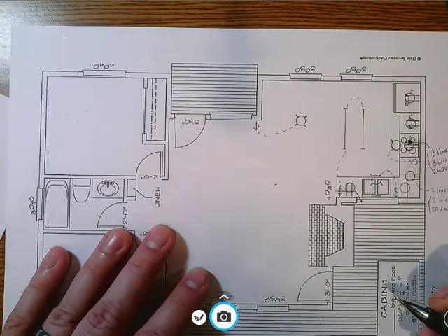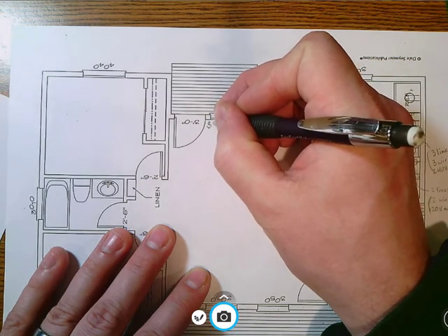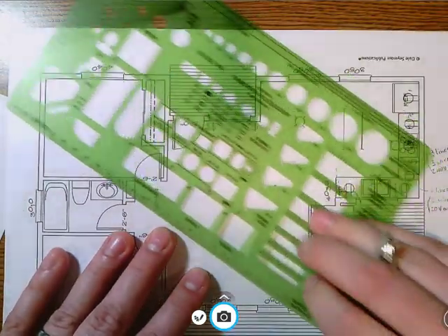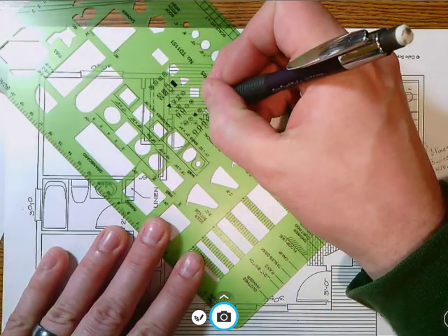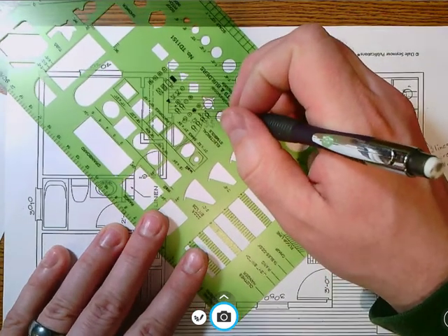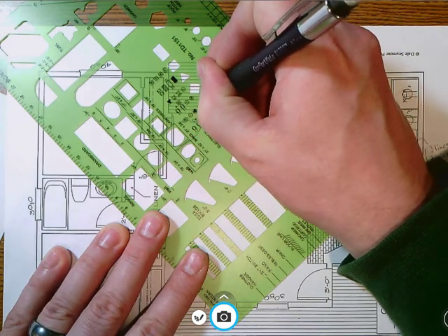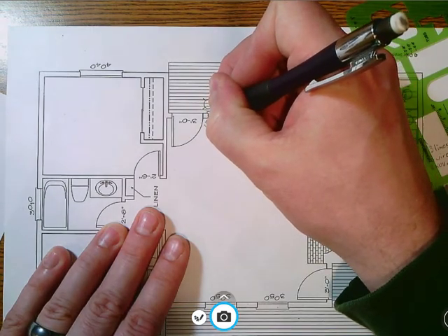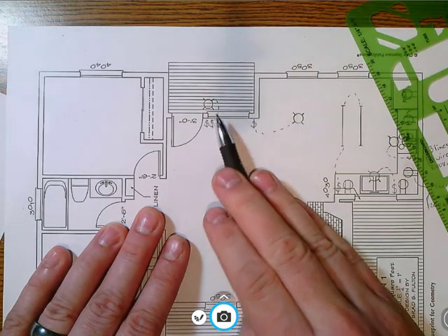So there's a couple things I'm going to do here. I'm going to put a switch here, and actually I need two switches here. The reason is I need one light on the porch, because every porch is required to have a light. That's one of the building code things that they establish here. So let's draw our circle, and then use this diagram to draw our lines. Have our nice light there. So we'll take this switch and just draw that dashed line. That switch is indicating for that.